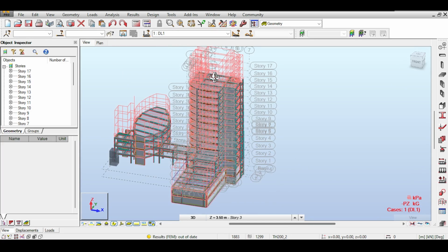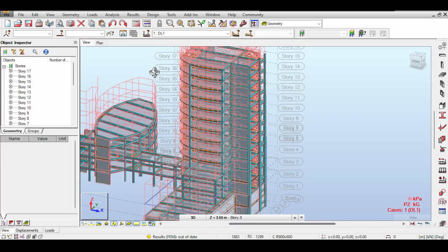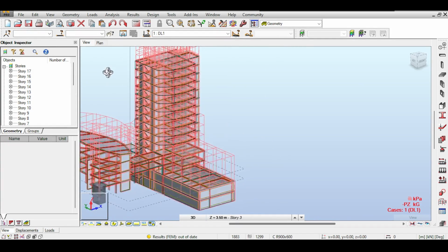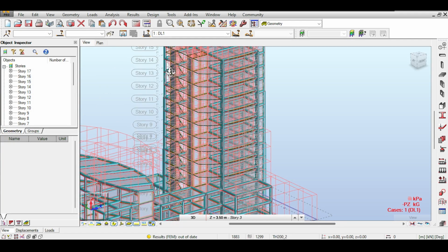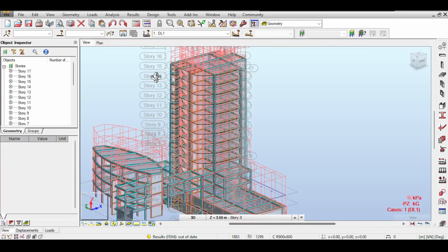Now, I'm going to choose to use claddings here. I want to mention something very quickly: if you want to apply a CFD analysis, then it's very important that you apply claddings or some sort of planar element. I think that without a planar element here, it would not register a wall, and it would basically apply the CFD on the beams only. So that's my take on it. However, I'm not going to do this.